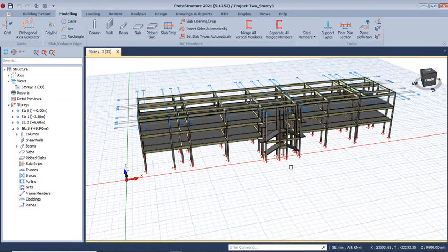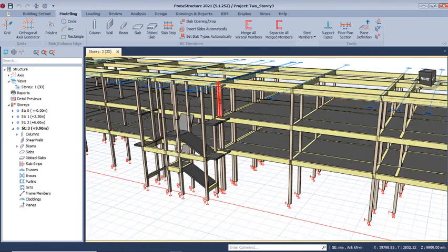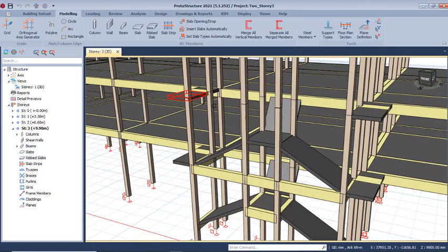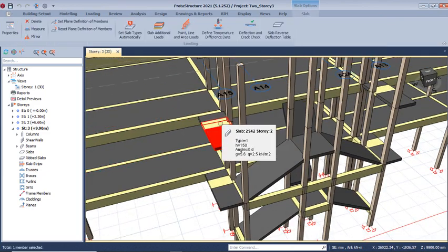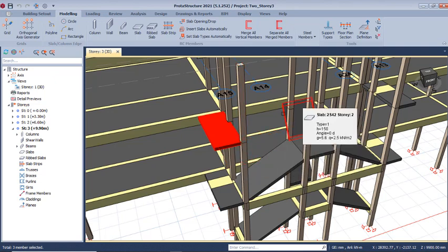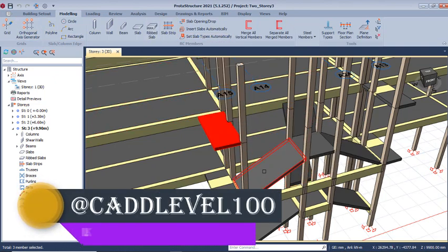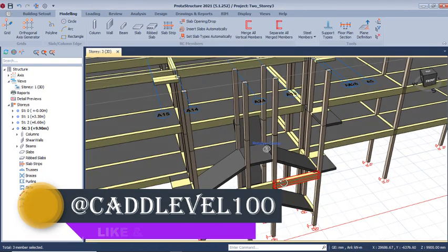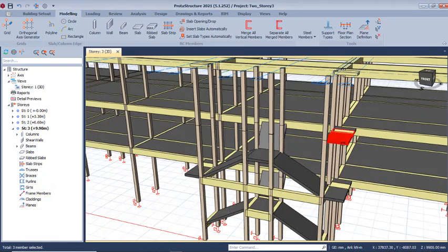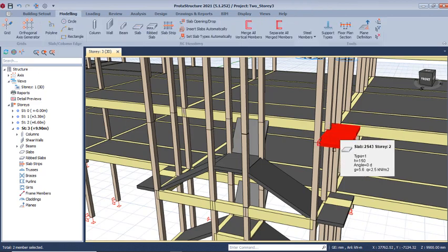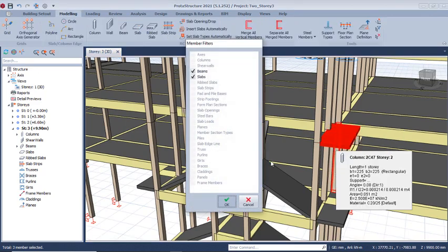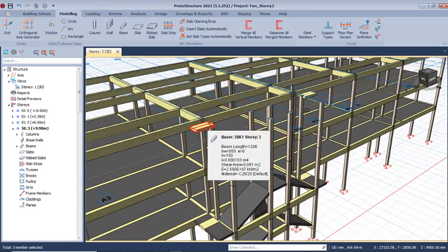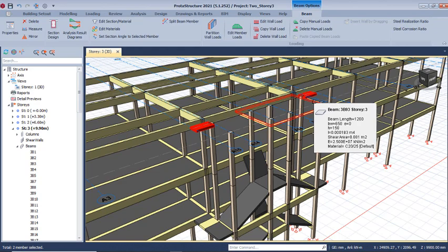Okay, so now we are having the roof beam just like this. So you will notice that we still have this because we include slabs, so we need to delete this again because this is the last floor. Okay, so we delete that. Yes options to delete that. Then you have to also delete this one just like this. Okay, all right, so having done this successfully, we need to also delete this one just like this.